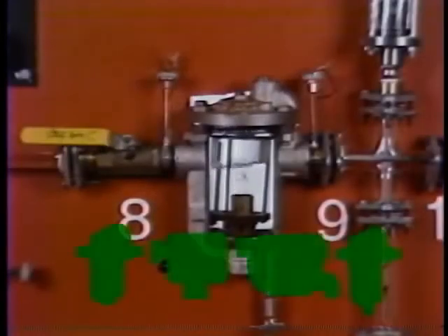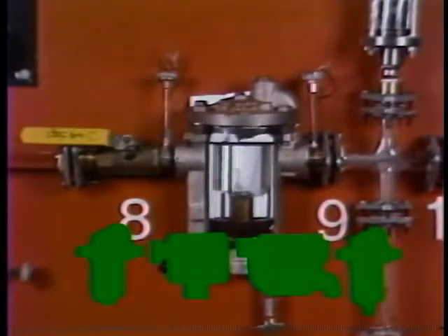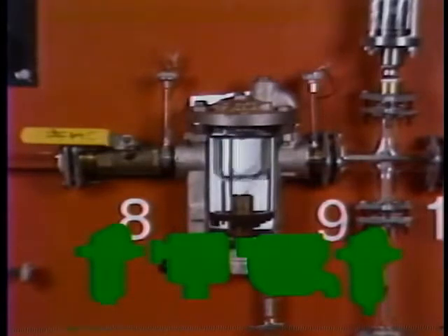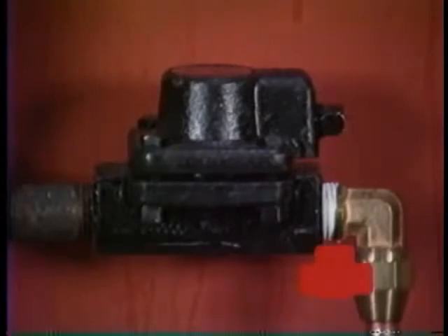Since the differential pressure across the trap provides the force for drainage when the trap is open, the best any type of trap can do is operate at a reduced capacity when the back pressure is increased. An increase in back pressure to a disc trap increases its cycle rate. If the cycles become fast enough, the trap may reach a point where it machine guns. Back pressure may increase to the point where the trap remains open, blowing live steam. Where high or fluctuating back pressure occurs, the disc trap is not recommended.